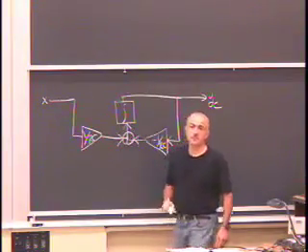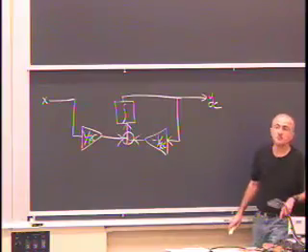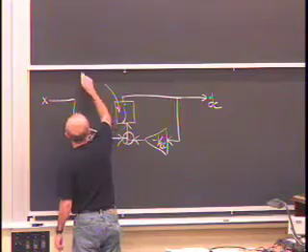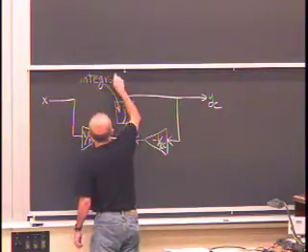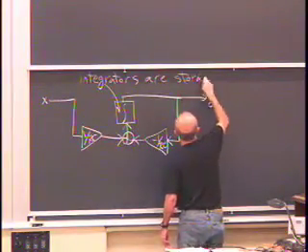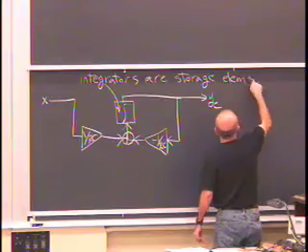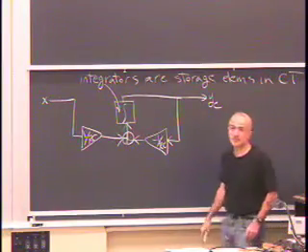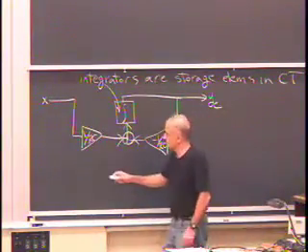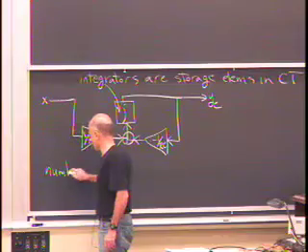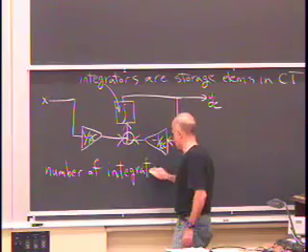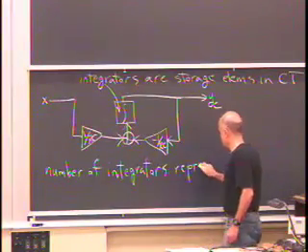and integrating. How many integrators do I have? That's the storage element. So these integrators are the memory elements. Integrators are the storage elements for continuous time. And the number of them represents the order of the system. So number of storage elements represents the order of the system.